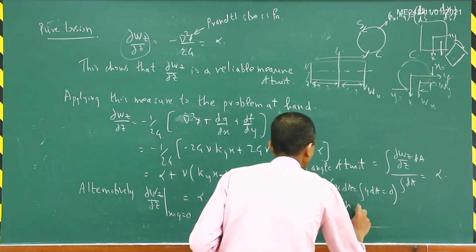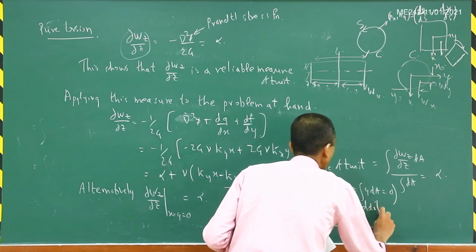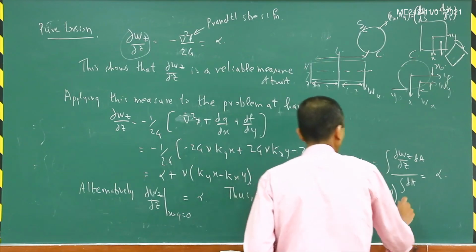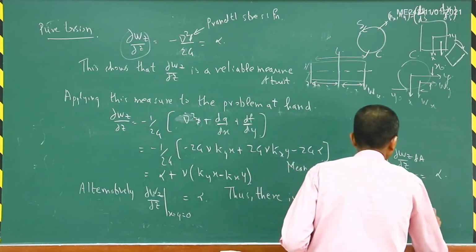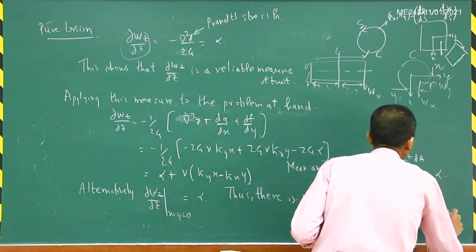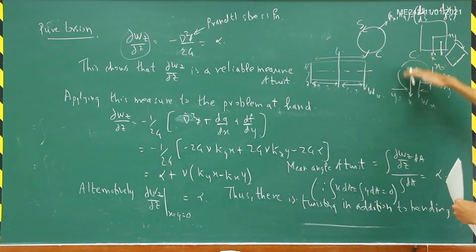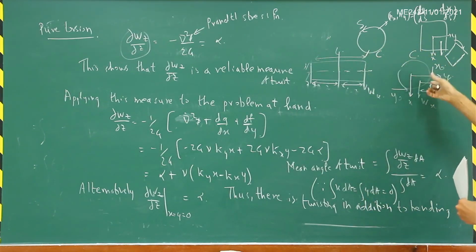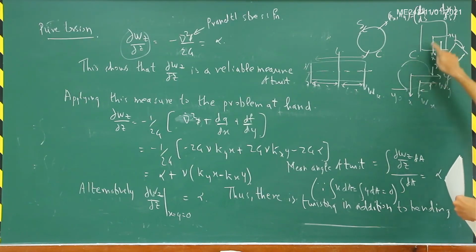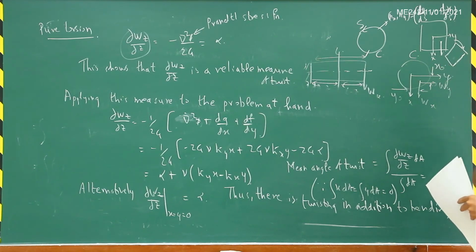In addition to bending of the cross section. Of course, bending means it is just bending down in this particular direction here, and also there is a twist of this particular cross section. So if the load doesn't pass through the symmetry axis in this particular example, this is basically the concept of shear center.